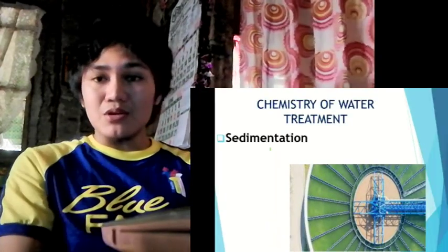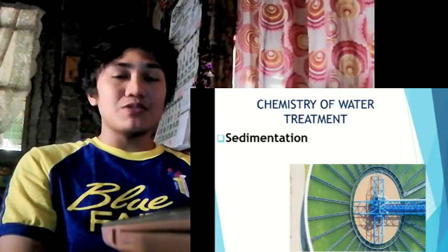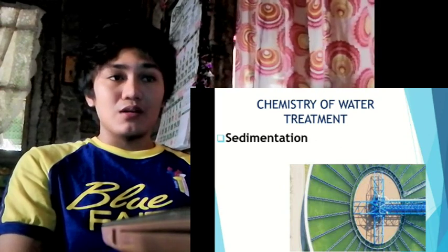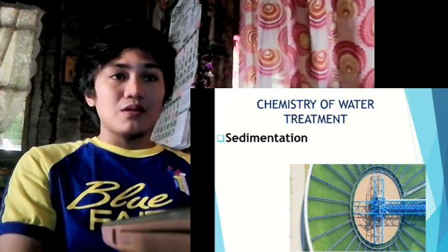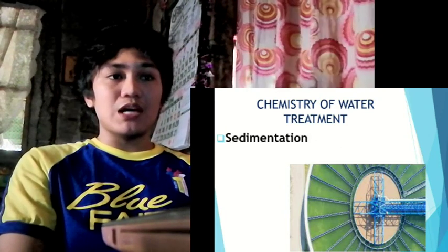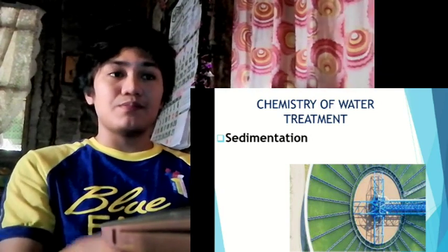The sedimentation concept: there are two important terms to understand in sedimentation zone design. The first is the particle or floc settling velocity, and the second is the velocity at which the tank is designed to operate, called the overflow rate.